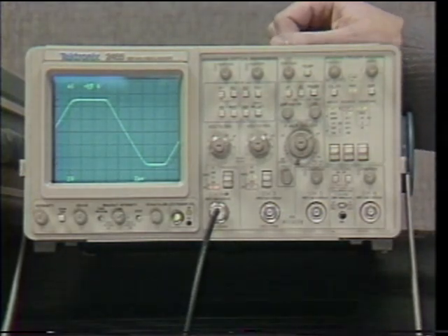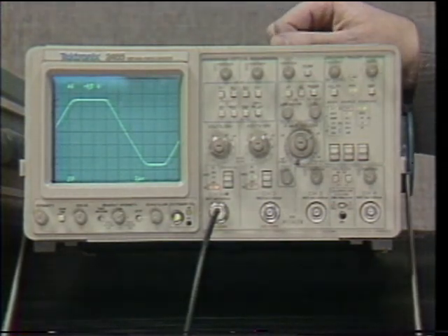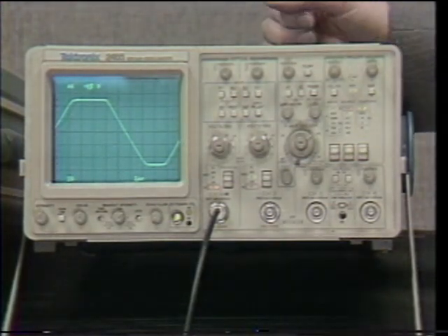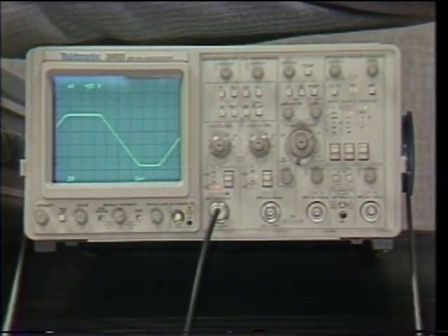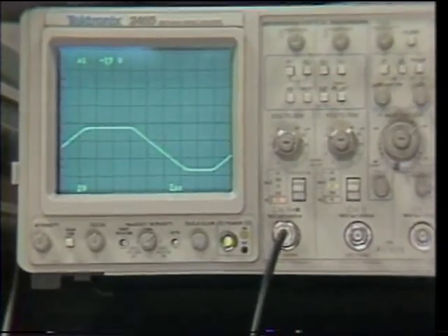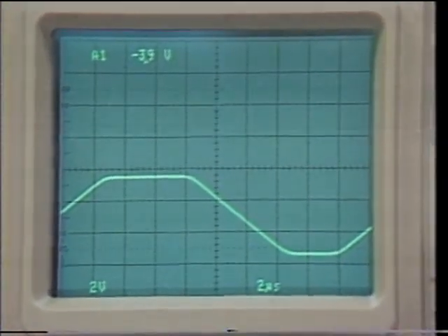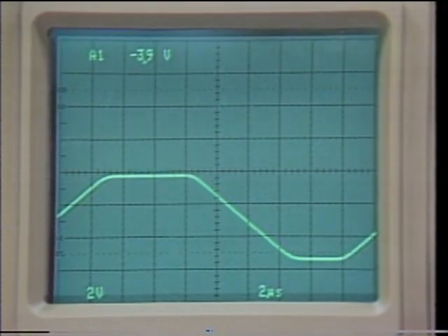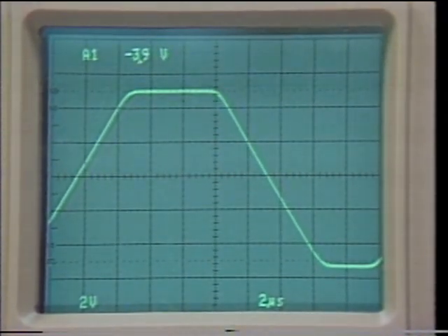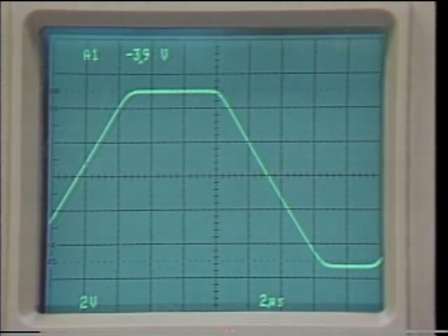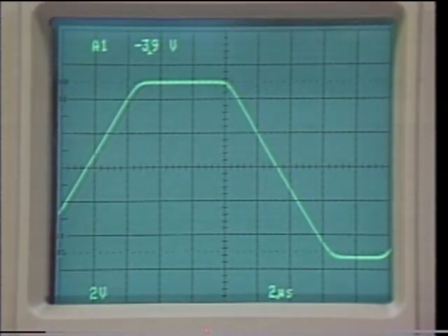The scope will set the trigger level automatically under any one of 3 conditions. The first condition we'll show is the loss of triggering due to a change in the triggering signal. Now, if the signal changes again, notice that the trigger level remains constant. And this brings about the second means of reacquiring the trigger level range.